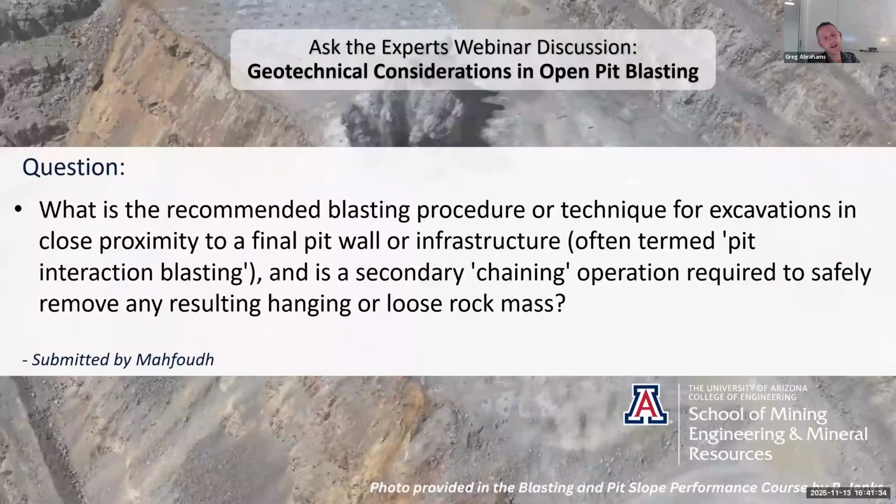Yeah, and I think that with the chaining, I'm seeing more and more a reluctance to drag the chain behind the dozer just from a safety side. I don't know what you guys are seeing in the industry, but people seem much keener on having a good operator in a track hoe scaling the face. And in extreme cases, you might hydroscale it if it's a critical piece of infrastructure. Hydroscaling is an effort, but it can remove huge amounts of loose rock.